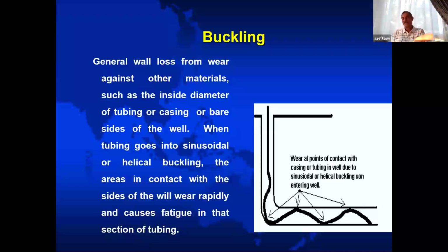If you reach this buckling, and if you didn't notice that and you keep pushing, you see these nodes, which now may be apart 1 meter from each other. If you keep pushing, these nodes will come closer to each other up till what we call lockup, where your pipe will be like a spring. If you reach lockup, forget about it. You will not be able to move here or there.